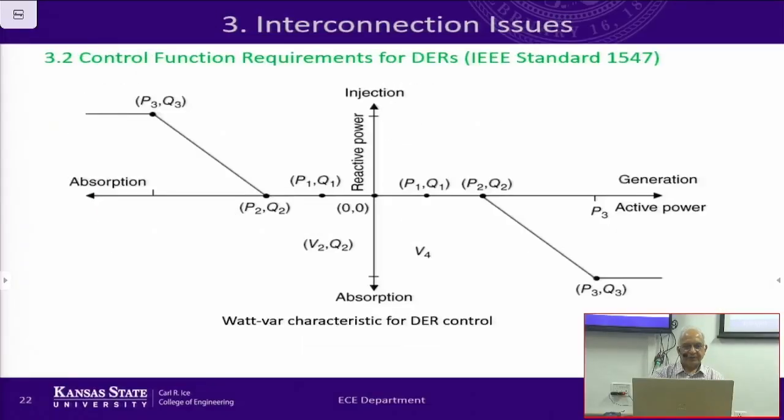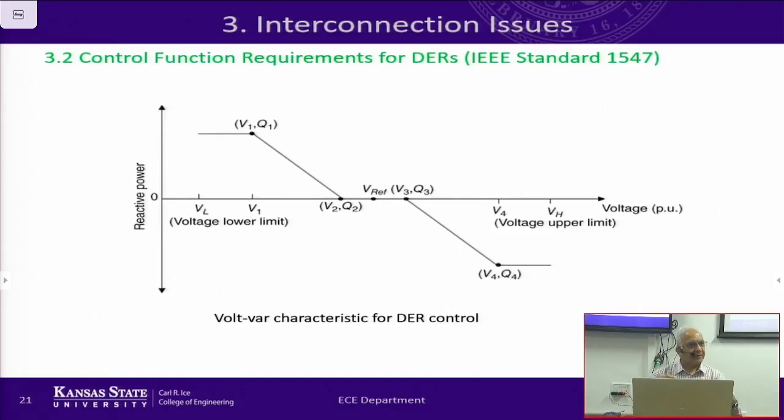Sir, the similar reactive power control can be used for wind or something like that also? Wind? Oh, yeah. The controls can be applied. These control mechanisms I showed in the graphs are not only for solar, they are for any distributed resource. So wind is included, batteries, all kinds of resources are included. This is general for DER, not exclusive to solar.